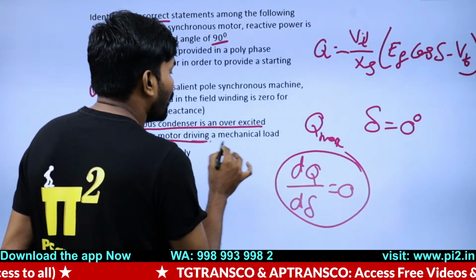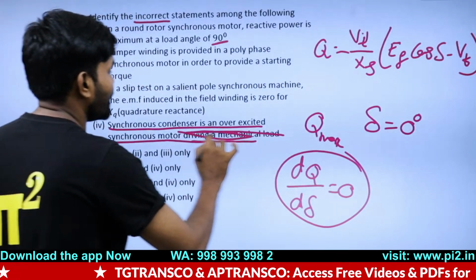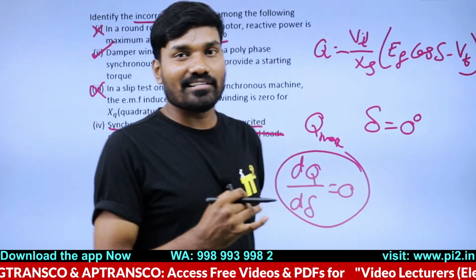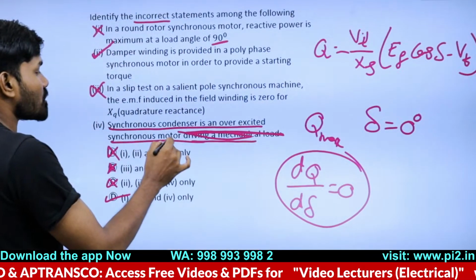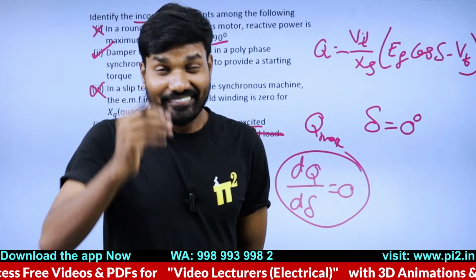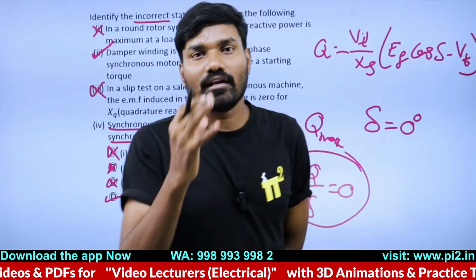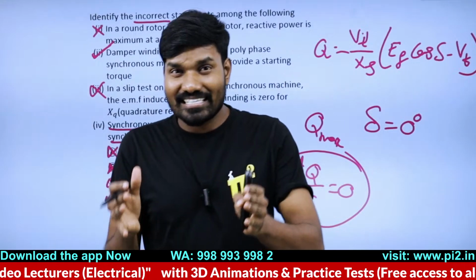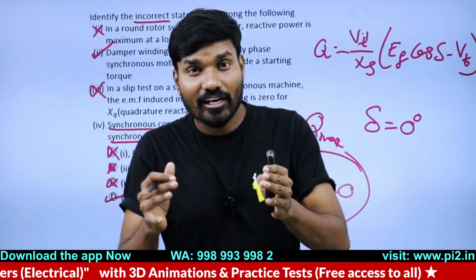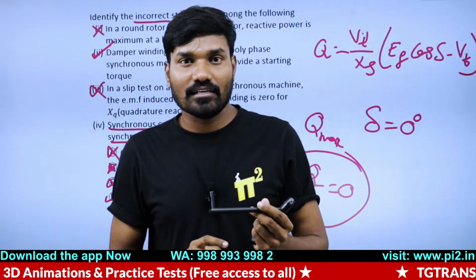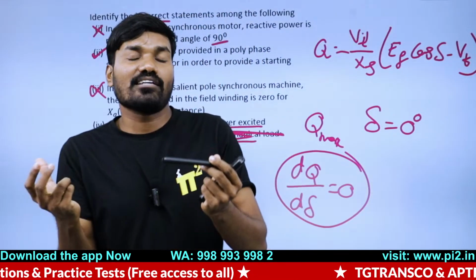Driving a mechanical load, no, this is not wrong. This part is making this statement wrong. Synchronous condenser means it is an overexcited synchronous motor at no load, when it is operating at no load. That's the difference between a regular synchronous motor and a synchronous condenser. You call it a synchronous condenser because there is no shaft extension. Synchronous condenser has no shaft extension.